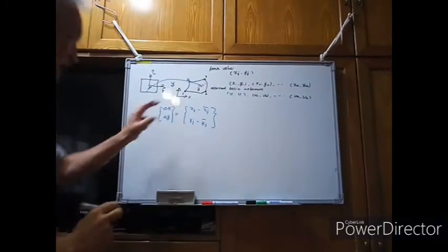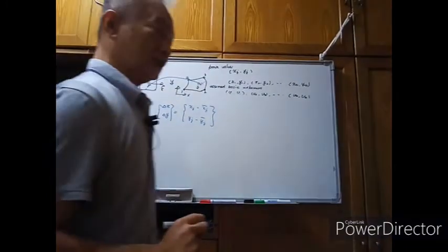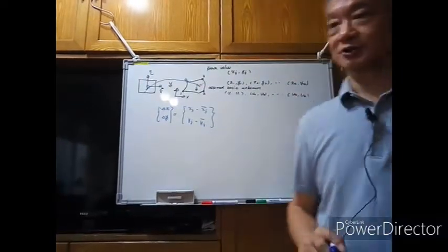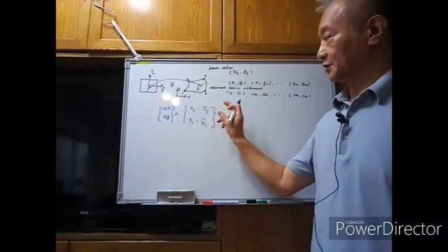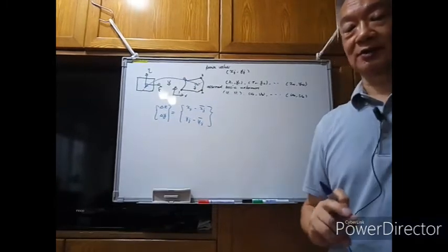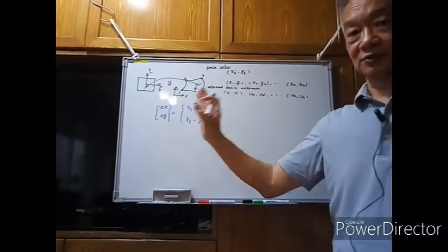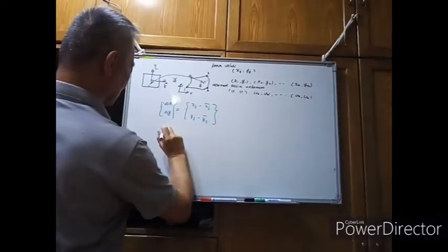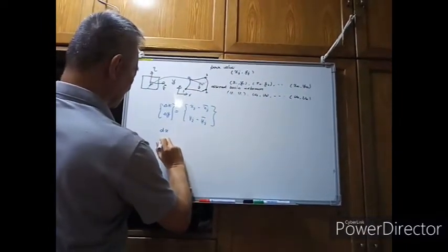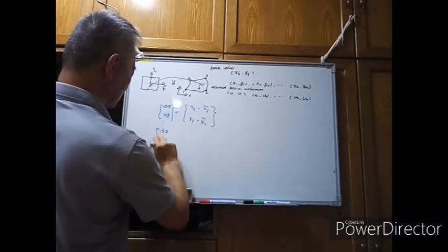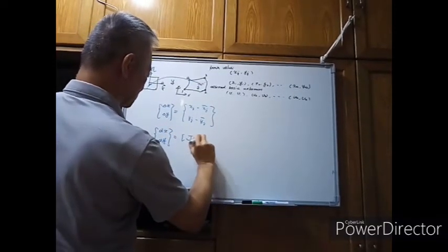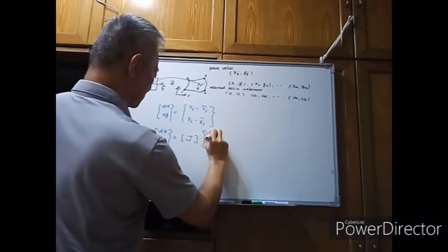So we can calculate the difference between the input xj and yj and the calculated xj bar and yj bar. But remember, most of the time they are different. Also remember, we have the formula: dx and dy will be the Jacobi matrix times dc and d eta.